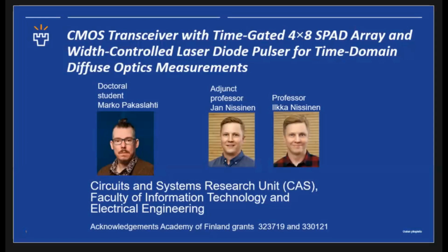The transmitter is a laser pulser with adjustable pulse width, so that the current pulse is useful for different types of laser diodes. And the receiver is a time-gated, time-resolved 4x8 SPAD matrix.